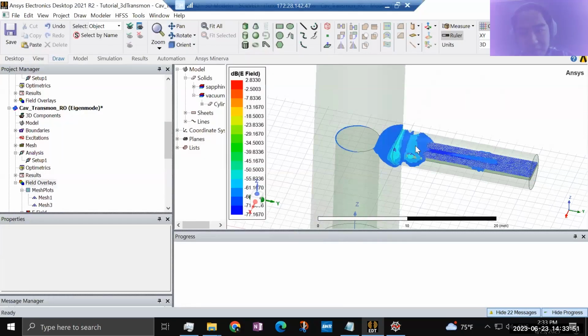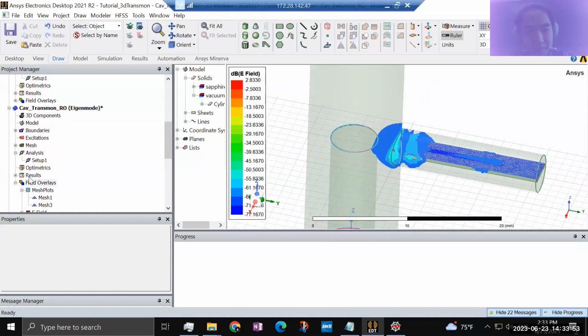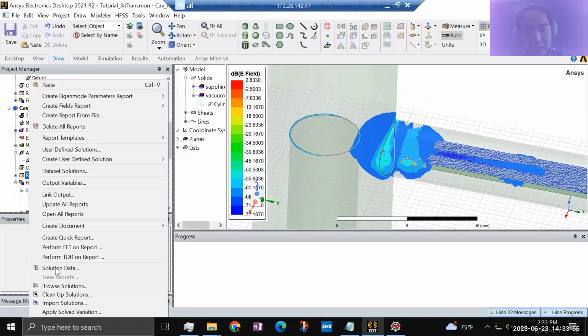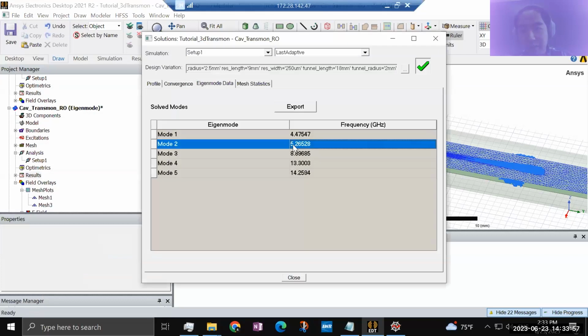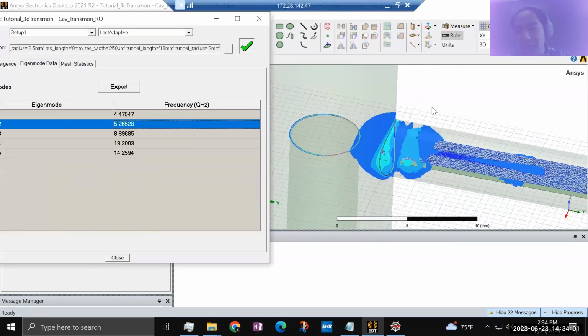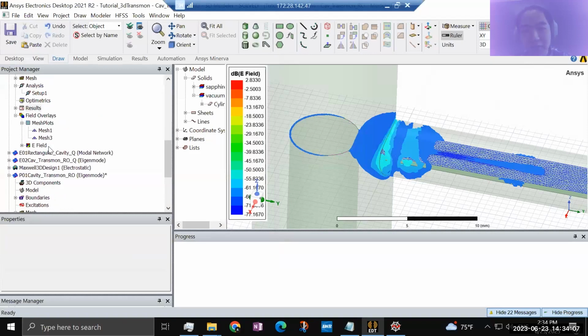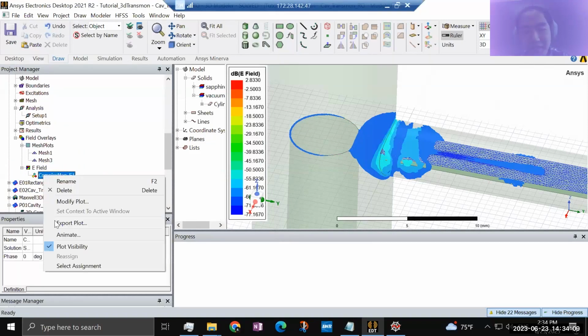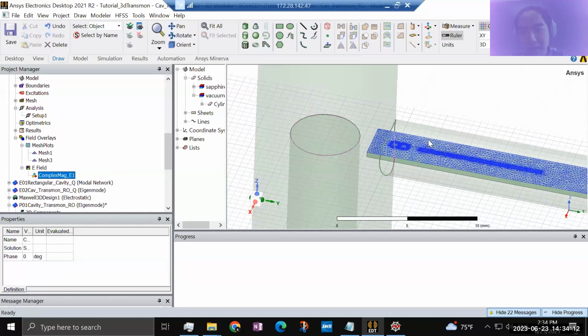Yeah, so this is the second eigenmode of the system that it has simulated. It's an eigenmode at 5.3 gigahertz. And you can see the E field structure is very localized, confined around the junctions, around the qubit paths. So yeah, the E field is mostly here. So that's how we confirm which mode is which. This is the qubit mode.